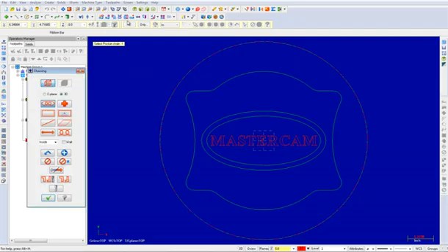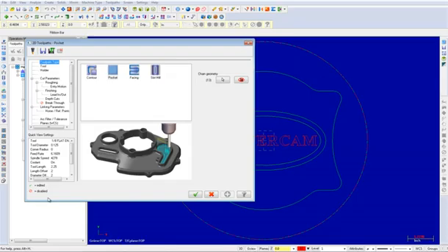When the chaining dialog box appears, choose the last button to reselect the chains used in the previous toolpath. Once complete, select the OK button to exit the chaining dialog box. On the toolpath type page, Pocket will be selected. Next, we will select a 1/32-inch flat end mill from the library and set the tool parameters.